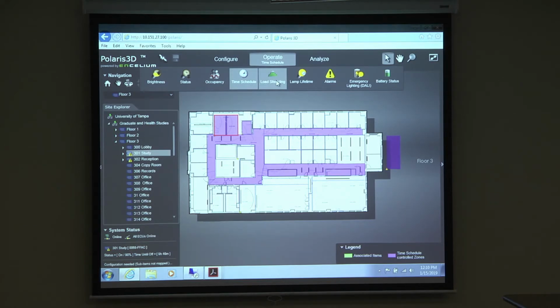I've actually done this at a couple of sites. In some cases they send requests to BACnet, the BACnet sends it back, and this device has them start dimming throughout, and then they get compensated for that. And just for the record, this is different from daylight harvesting. So the question is about load shedding versus daylight harvesting, and they are different.